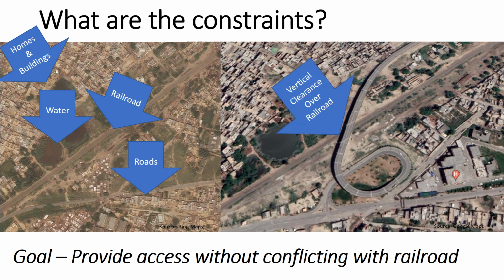So from the after period, the geometric design constraints are the vertical clearance over the railroad, and then the slope of the loop. And that's really what we come back to, and that's why the loop is employed here, because that slope is very important. We can't have too steep of a road, or in particular heavier vehicles, large trucks, can't navigate up a really steep roadway.